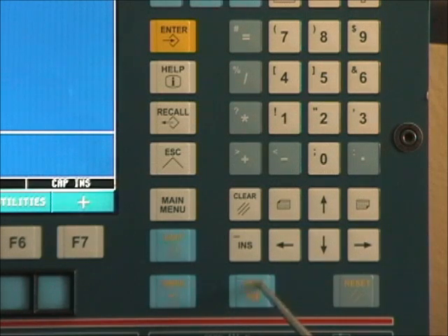We have area 6, the shortcut keys. This is the edit shortcut key, the simulation shortcut key, and the execute shortcut key. In edit, to go immediately to execute, press execute, and that will pull up the execution mode without having to select the program. It uses the program you are editing. In simulation mode, it pulls the editing program and puts it into simulation mode. If you're in execute mode and you wish to edit the program, press edit and it will pull up the existing active program that is being executed. Prior to using these keys, remember to press feed hold or reset.